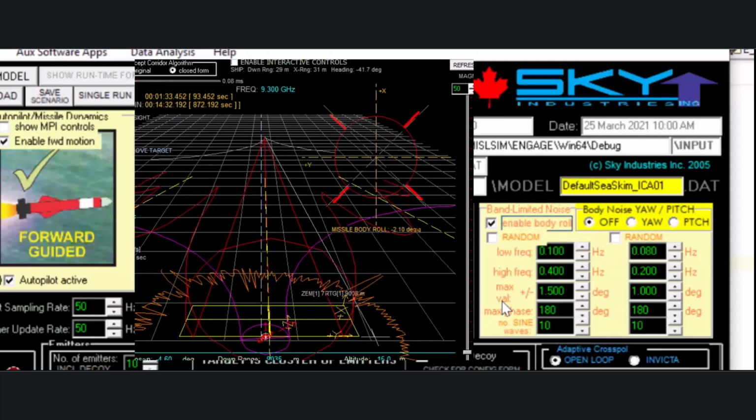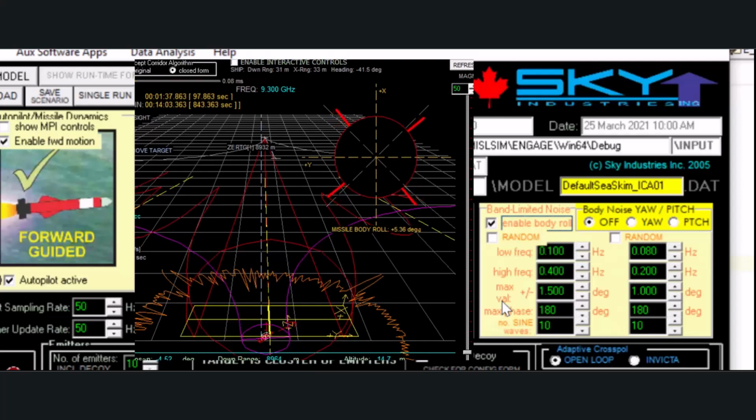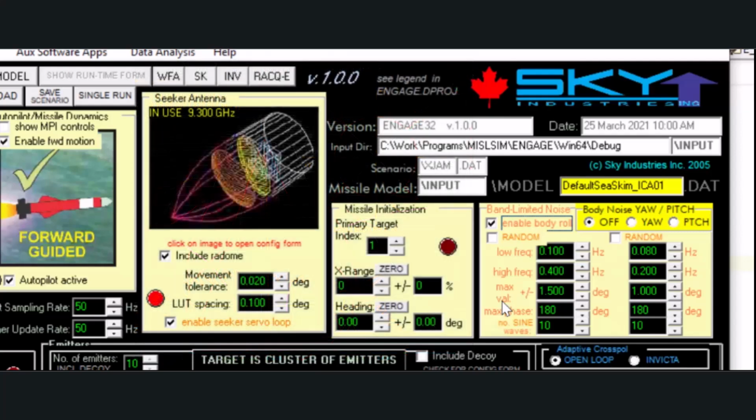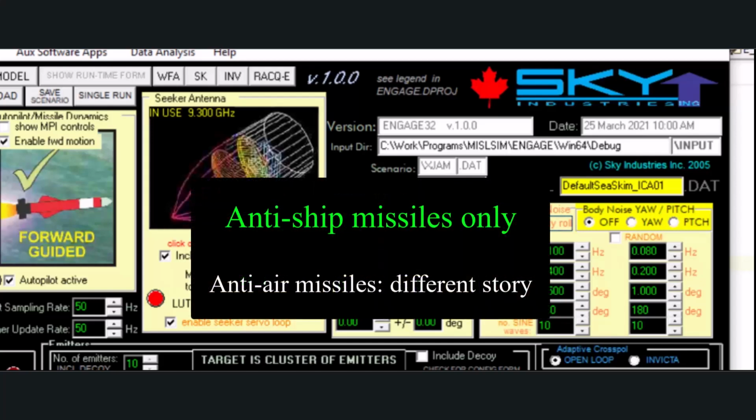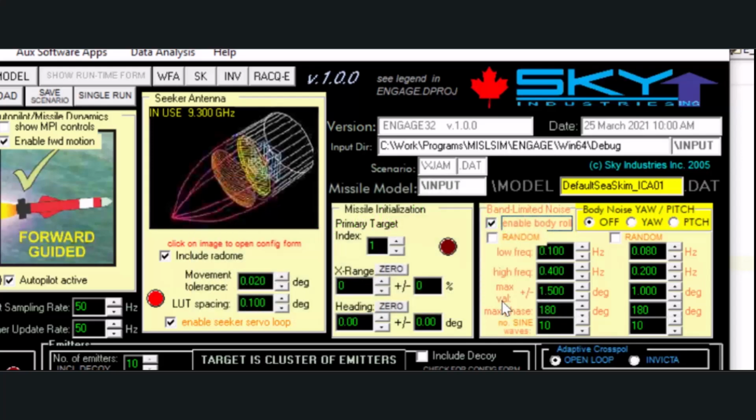So how do we design our countermeasures to accommodate a rolling missile? Now, missiles don't roll. None that I know of roll to turn. They're all skid to turn. And the reason is because the autopilot model or design becomes horribly complex, because the elevation and azimuth autopilots are now going to couple into each other, and you don't want to get into that. And we also can do the same thing with the other two axes, like yaw and pitch.